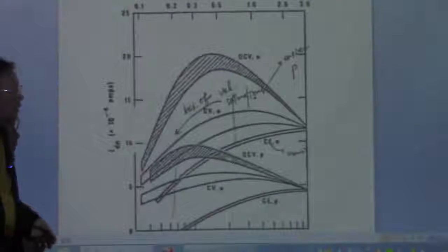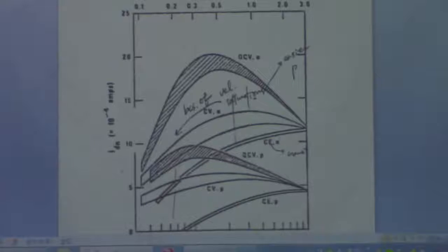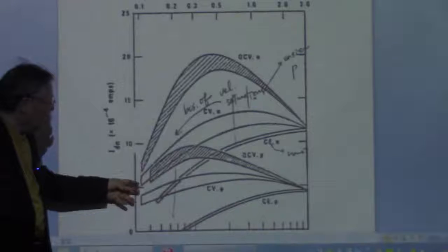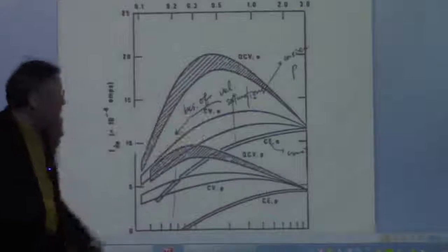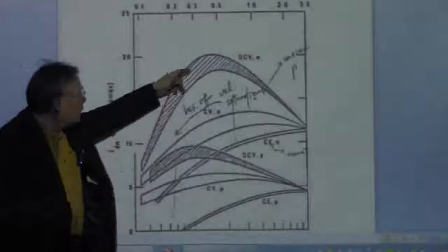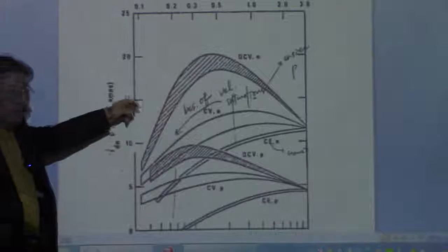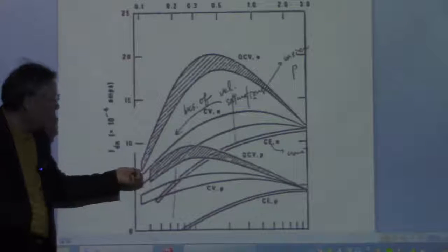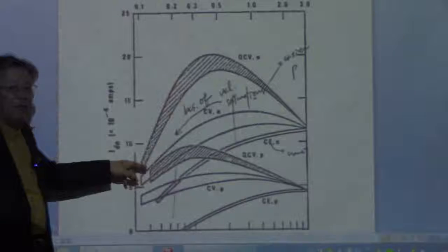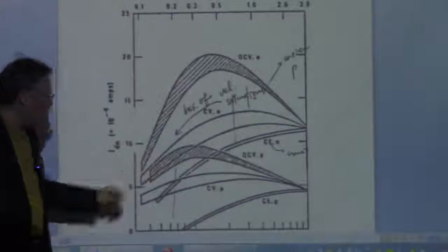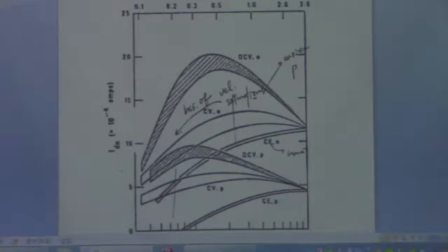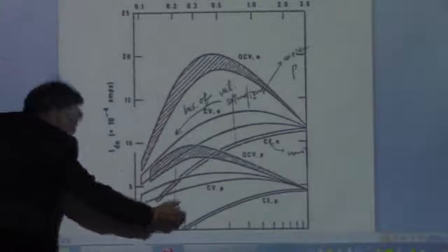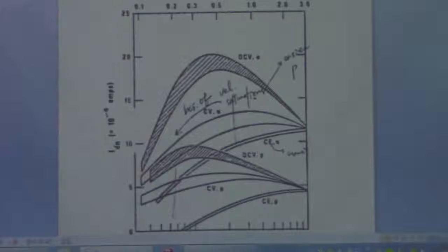So the NMOS is not much more beneficial than the PMOS by scaling in the case of constant voltage. Now, with quasi-constant voltage, which is a very industrial term, you begin to see the striking difference. It is not really beneficial to get an NMOS in the quasi-constant voltage case, which converges to the same values as you scale down your device.